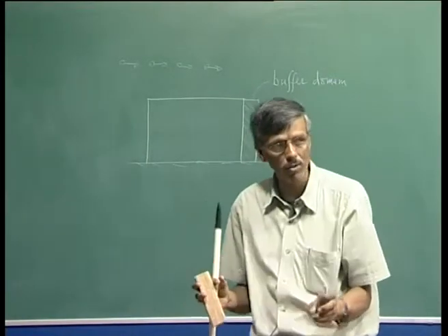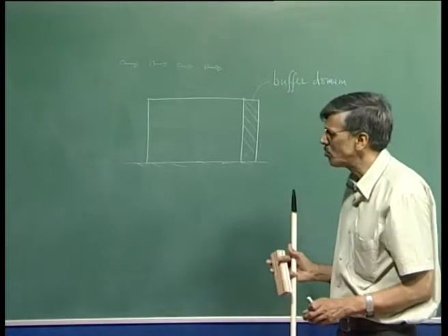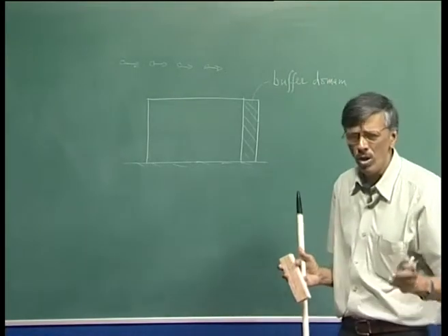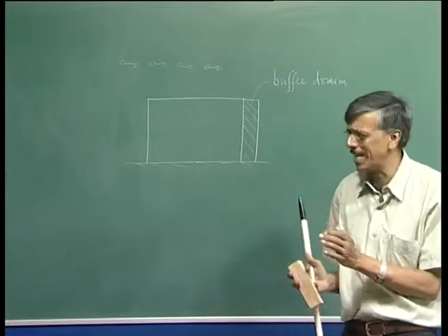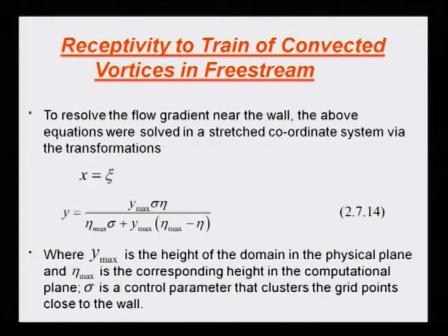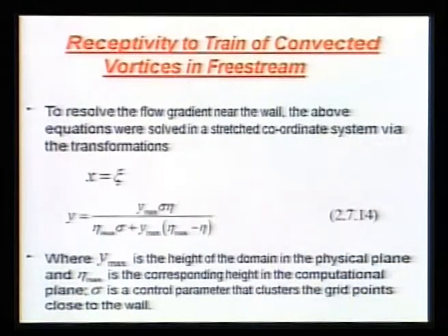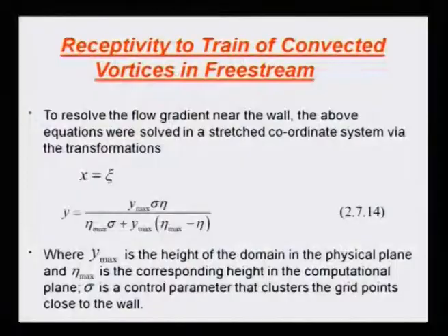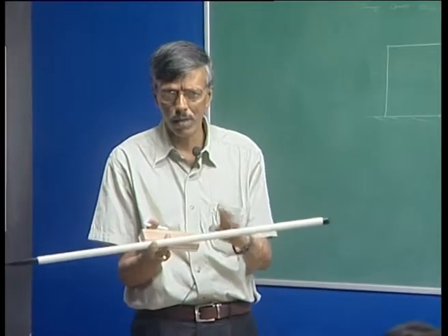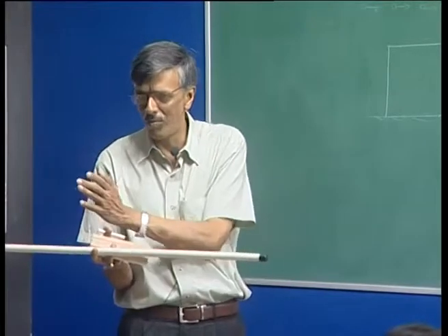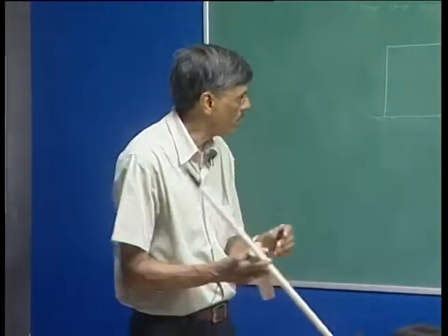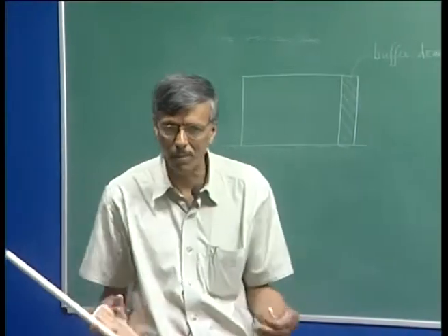That is what we are going to see. In the progression of that packet, we would not like to have anything other than uniform spacing in the streamwise direction, because there is no preference in the x direction. Because if I have a grid, sometimes the vortex will move past, sometimes it will be free, but we do not want to do a fancy time dependent grid.